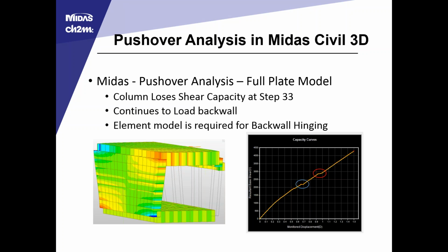We'll look into the detailing a little bit further in a few slides, but to point out, the areas of high stress concentration on the bottom and top corners of the back wall do show that we'd likely get a little bit of yielding in those sections in the event of an extremely strong earthquake. However, that dissipated fairly quickly. We expect that to lose a little bit of cover. We just want to confine that steel and make sure that the longitudinal bar stayed intact.